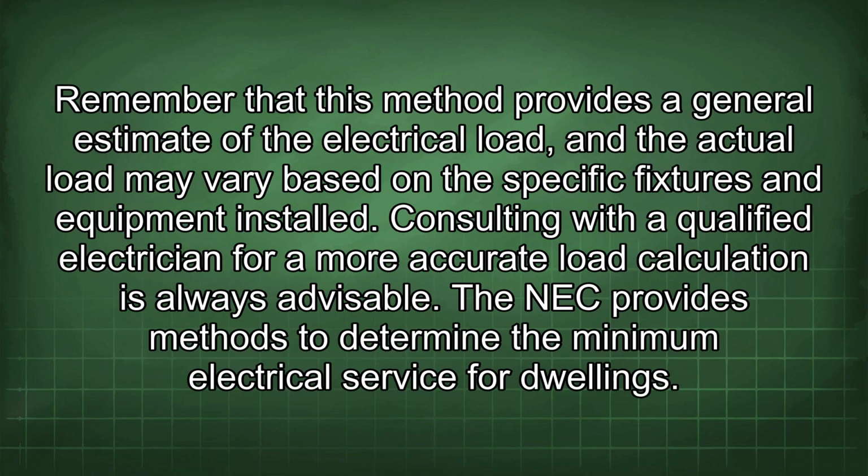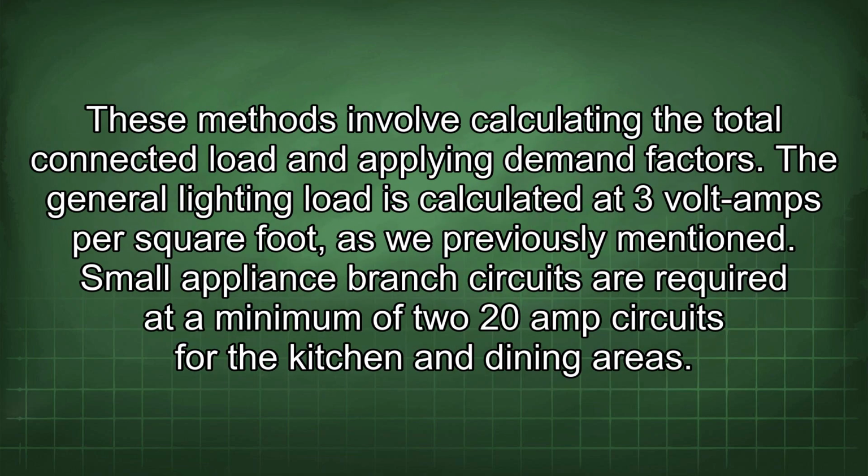Remember that this method provides a general estimate of the electrical load, and the actual load may vary based on the specific fixtures and equipment installed. Consulting with a qualified electrician for a more accurate load calculation is always advisable. The NEC provides methods to determine the minimum electrical service for dwellings. These methods involve calculating the total connected load and applying demand factors.